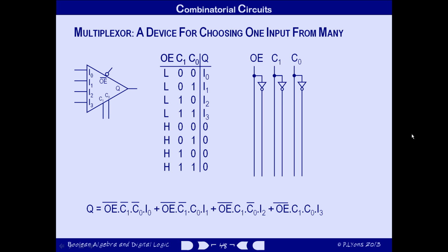You'll notice that just as we've broken the usual conventions for drawing up truth tables, so we've broken the usual convention for drawing circuit diagrams, in that not all the inputs and their inverses are listed down the left-hand side of the diagram. The 3 control inputs are shown conventionally, but the inverses of the data inputs are never used, and each of them only contributes to 1 term in the Boolean expression, so we've input them from the left, directly into their own individual AND gates.